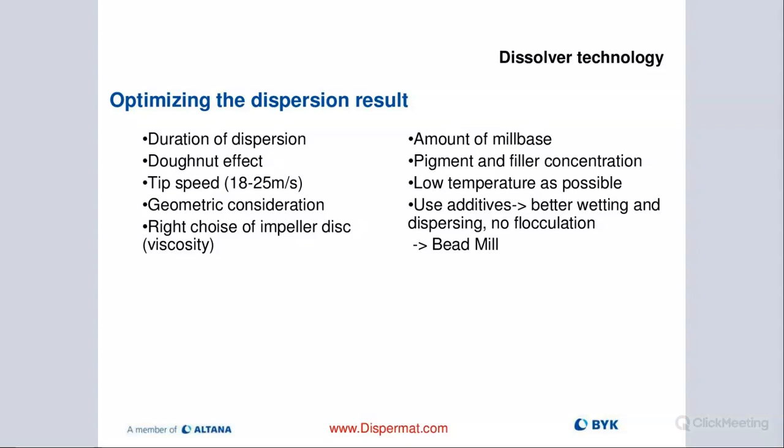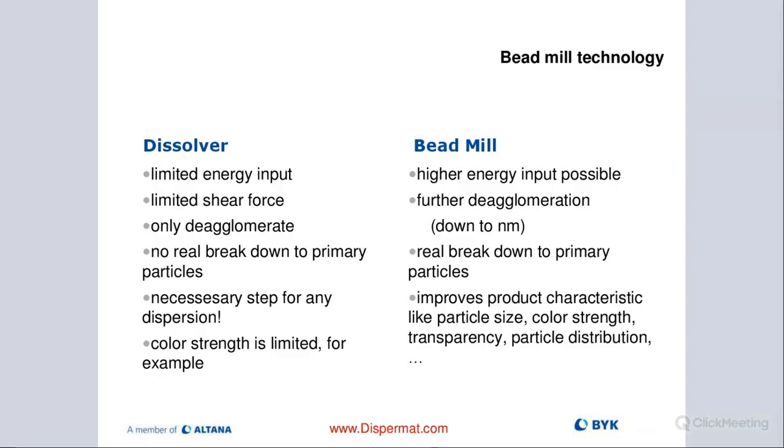It can make it a more difficult or tedious process to move product from one container to another if you have a lot of air. For that purpose, we also have vacuum systems that can help you, or the right defoamer can also do the trick.